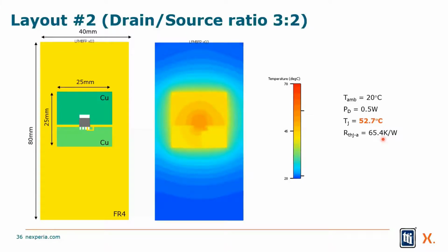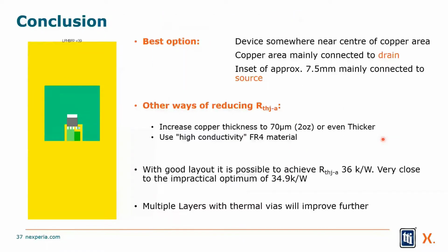If I can keep pushing that number, I will have the maximum efficiency, which allows me to put more power into the MOSFET without overheating the junction, because I have a good way for the heat to flow out of the MOSFET package into the circuit board itself and then be dissipated safely away.